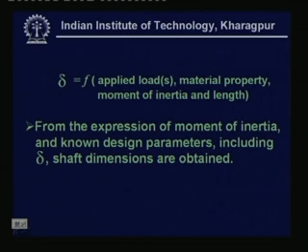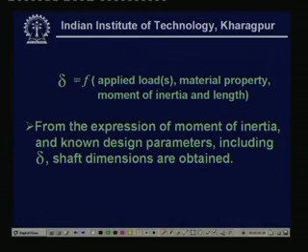That means this is the basis of the design. You find out this deflection as we have discussed earlier. Now, the moment of inertia comes into the picture, which means the geometrical dimensions, and other design parameters like load come into the picture, and the shaft dimensions can thus be obtained if we choose a suitable limit for delta.